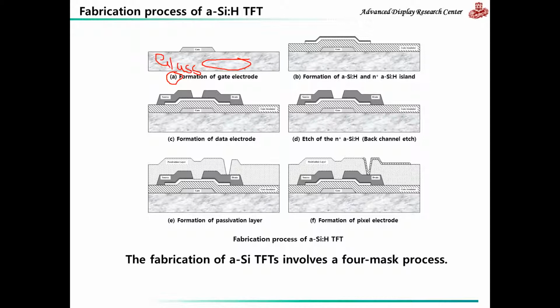And how do we define this shape? We use a design mask, the gate mask, to design the shape and size of the gate electrode. After we make our gate electrode, we deposit silicon nitride, which acts as the gate dielectric.